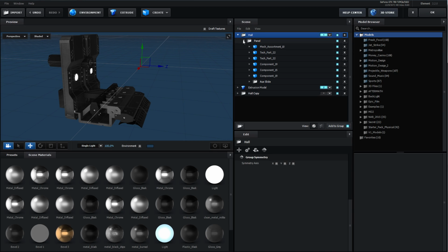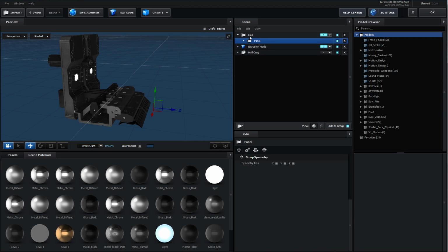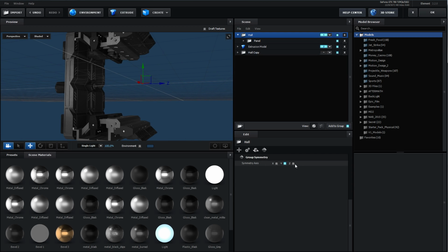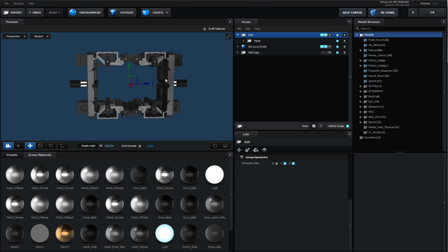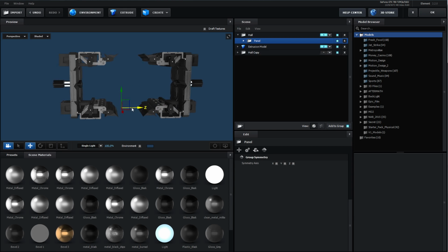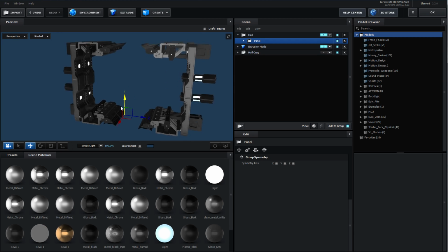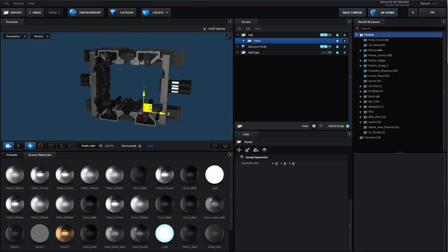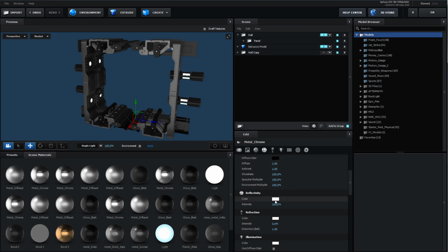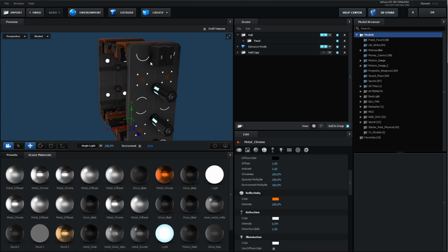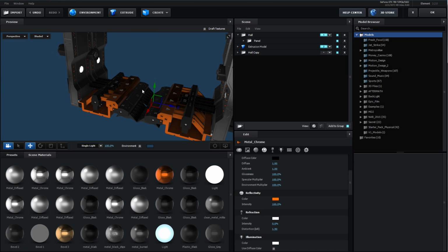So what I'm doing is taking all of the objects that are inside of the group, and I'm turning on the symmetry mode for the Y-axis and for the Z-axis. So that's how you can basically create repeated objects using the symmetry mode. And I can move any of the objects that are inside around, and all of the other objects will stay connected. And because it's an instance, I can take a material, say a gold material, and I can throw it onto one of the components, and it'll update for all of the components that are referenced by that same instance.